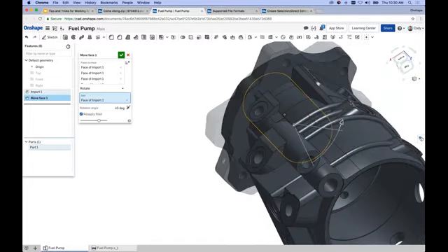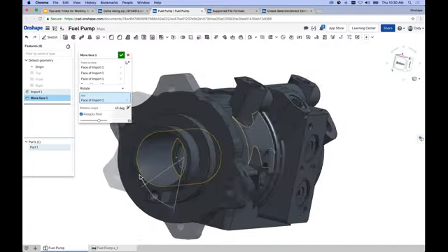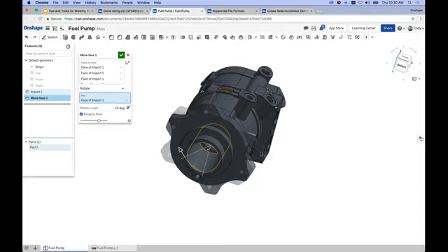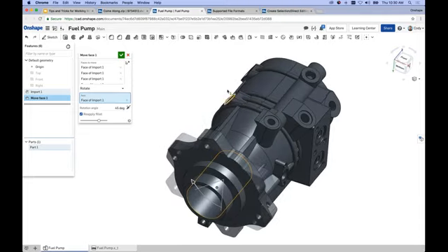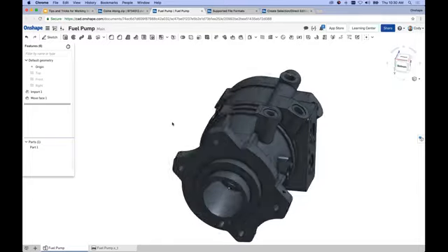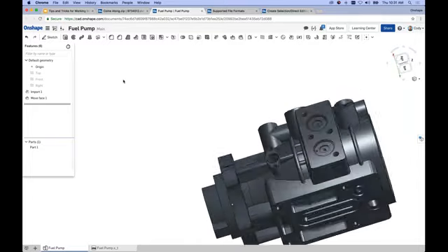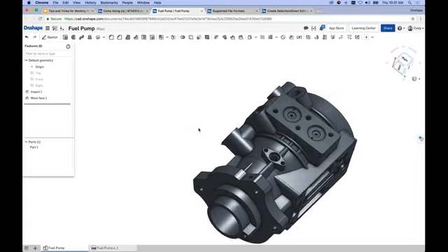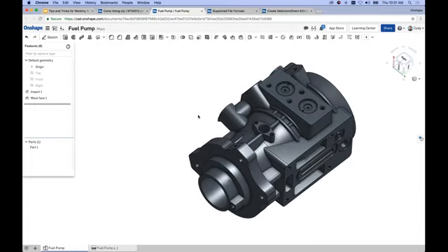But it allows me to grab that entire protrusion and spin it, right? And that's something that, without the original sketch and features that drive this, can be a very tedious thing to do in many systems. But move face in Onshape, very powerful feature, something I can't recommend enough, right? I hit the green check, and now I've rotated that entire flange 45 degrees, right? So that is the move face feature and the rotate option. I can't stress enough that move face is a very powerful one.